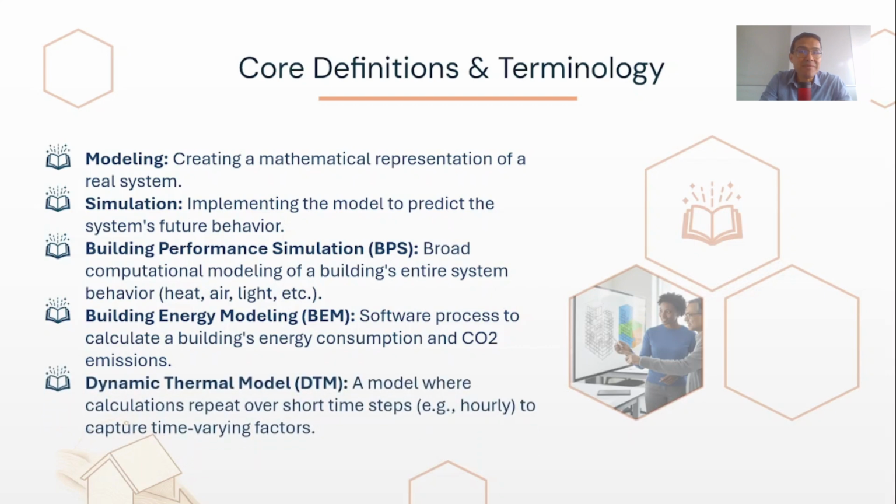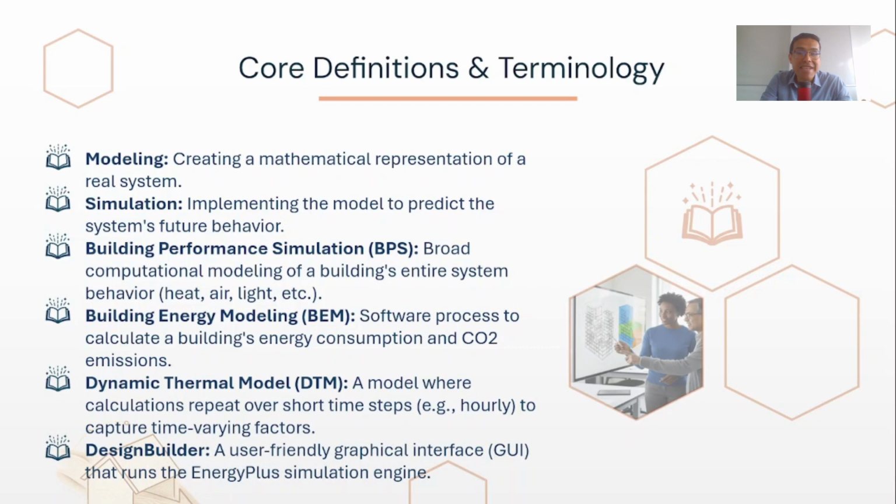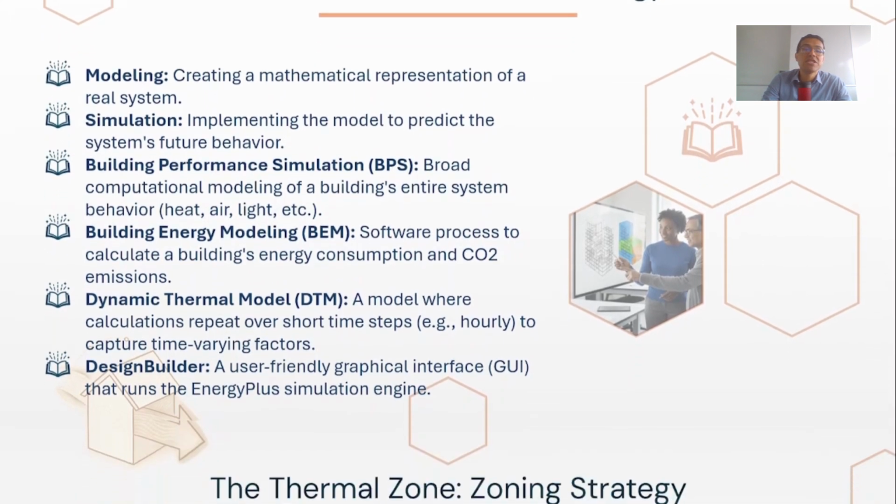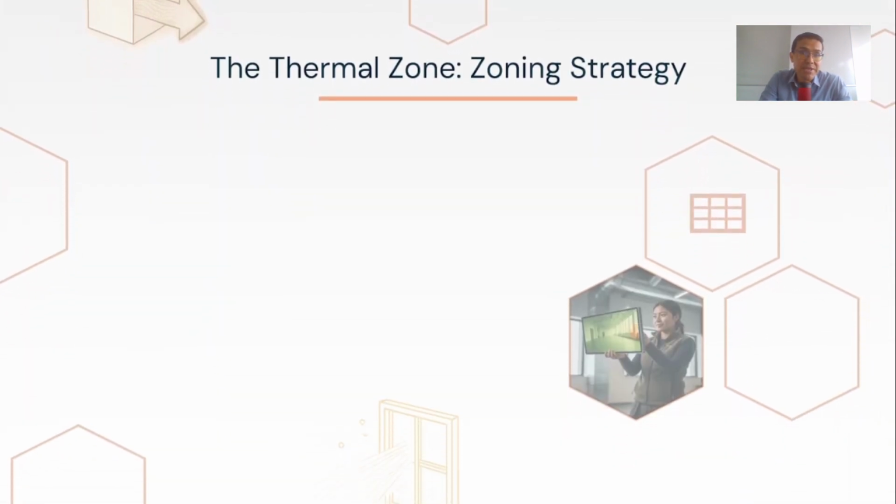The key to BEM is the dynamic thermal model. Unlike simple static calculations, a DTM repeats its calculations many times, typically on an hourly basis, to capture time-varying factors like thermal storage, changing weather, and shifting occupancy. This makes the predictions much more realistic. Finally, tools like DesignBuilder act as a user-friendly graphical interface, or GUI, that allows us to build and manage these complex models while leveraging powerful engines like EnergyPlus.